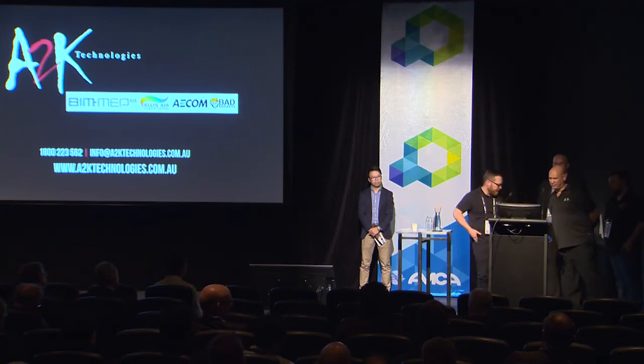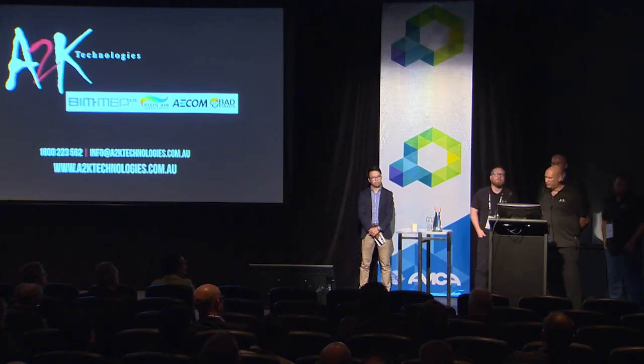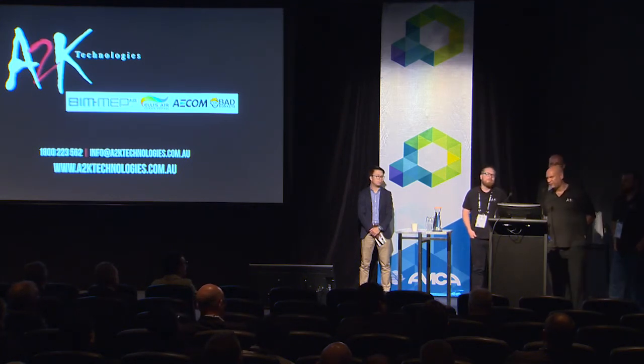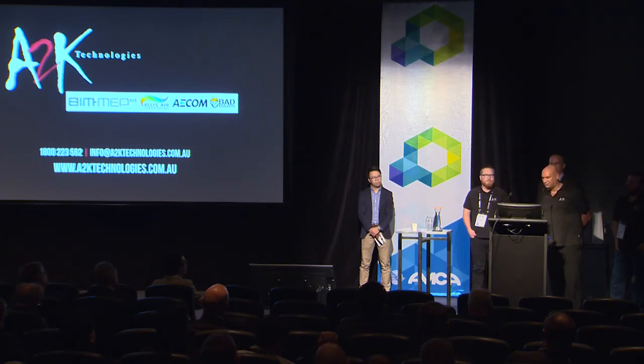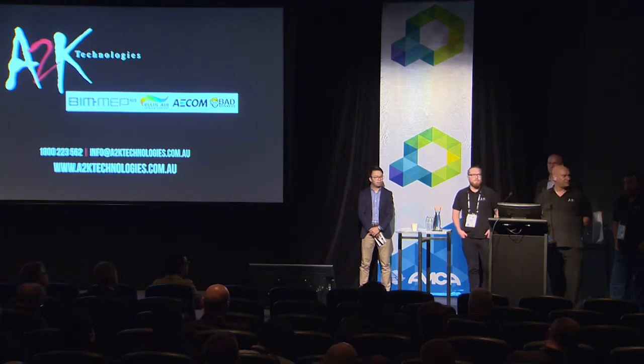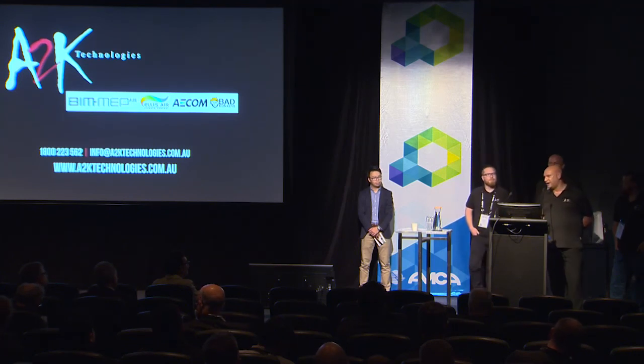Just to add to that as well, and I think Shannon Warwick may have touched on it this morning, we're looking at getting PowerCAD to auto size cable trays. And that's fabrication cable trays, not Revit family cable trays. We believe that the functionality of fabrication cable trays in Revit is much better than RFAs. So we're currently in the throes of, not to promote this, automating the design from cable sizing to the actual sizing of the cable trays in the model.